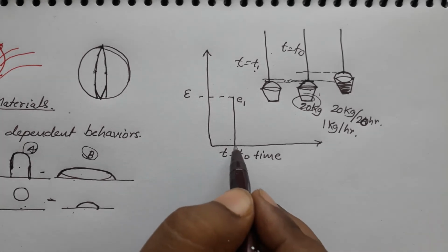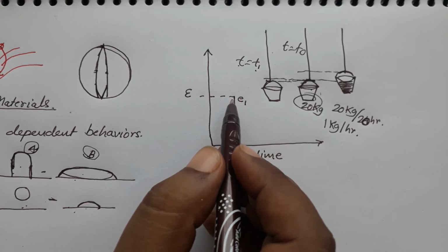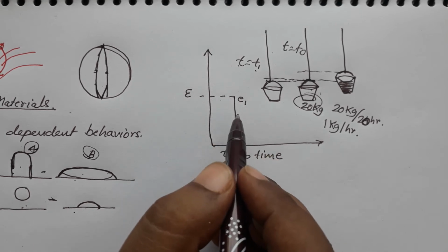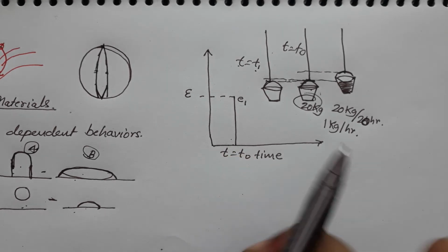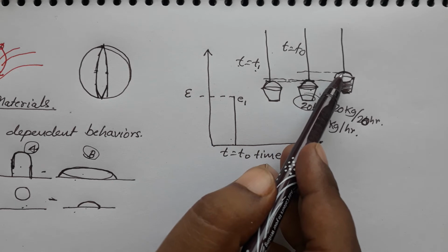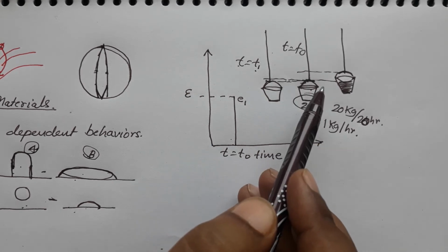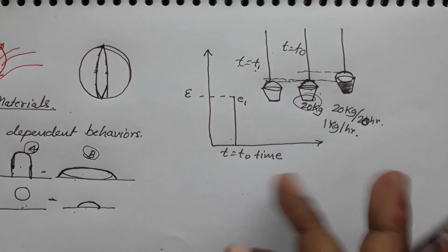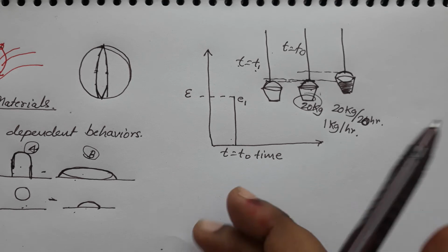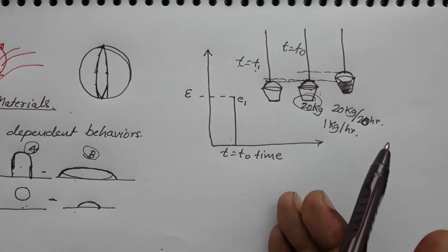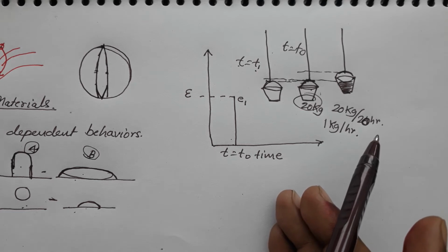So, in this case atoms are finding their new equilibrium position, right, and so the other meaning of this is when the instant load is applied, the atoms are not in equilibrium position, and this will cause a change in their own temperature. Okay. So, this process where the instant load is applied, the entropy of the system is not allowed to change because you have not given sufficient amount of time for the atoms to gain a new configuration. So, configurational entropy has not changed.